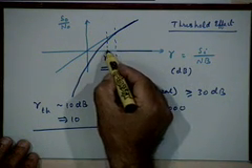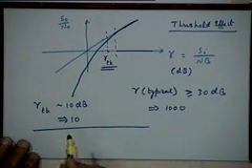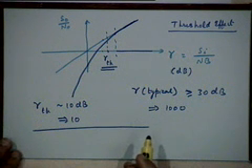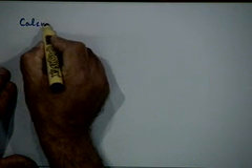You could define it here, or here, or here. You have to just agree on some definition and do the calculation accordingly. So what we will do is define the point of threshold in a particular manner and then calculate at what input SNR that point of threshold will occur. So let us look at a very typical calculation of the threshold SNR.